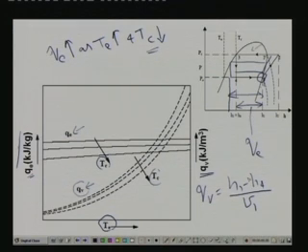Because you can see that there are two effects here. First effect is this: as TE increases, specific refrigeration effect increases marginally. So numerator increases. At the same time, when you are increasing the evaporator temperature, the specific volume of the refrigerant vapor decreases steeply. So numerator is increasing and denominator is reducing steeply. As a result, you can see that the volumic refrigeration effect increases quite rapidly with evaporator temperature, and it reduces as the condenser temperature is reduced.